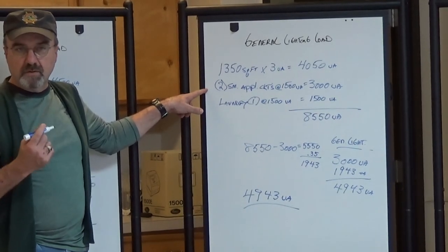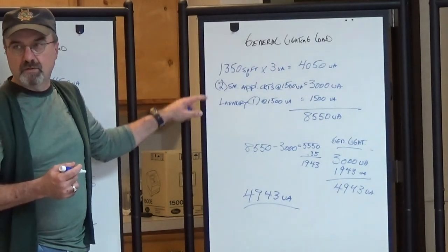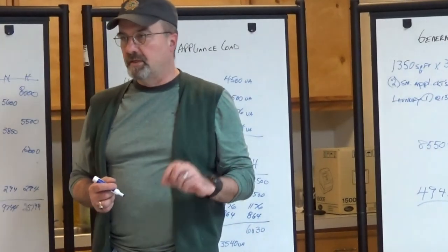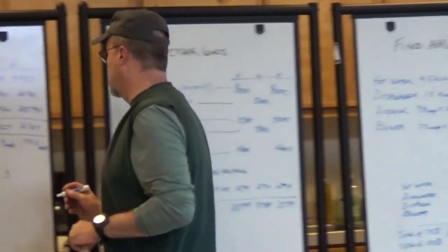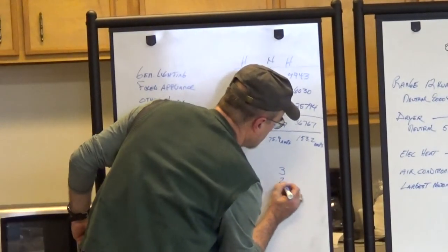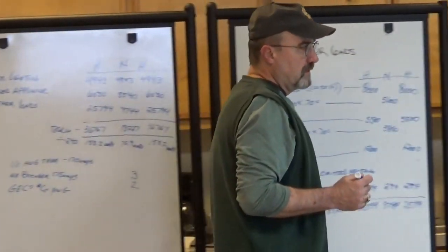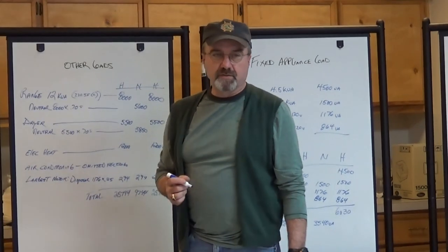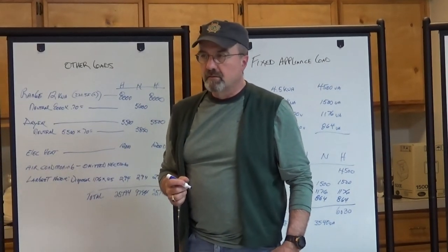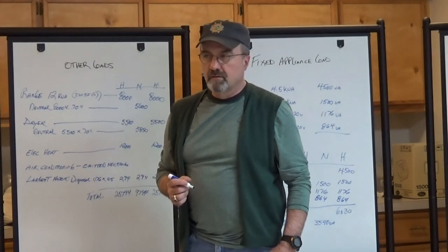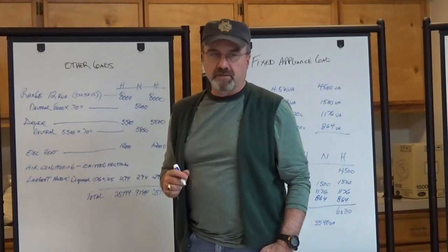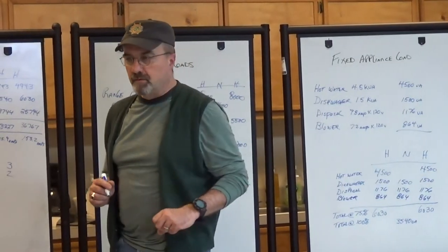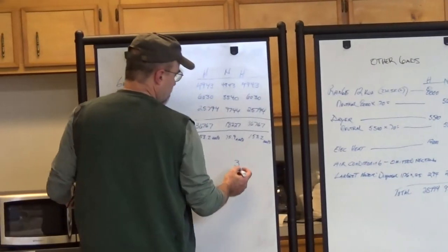That's 2 breakers at 20 amps, so 2 spaces. What else does the code require? One laundry circuit. That's one space in that panel board we need to dedicate for the laundry circuit.